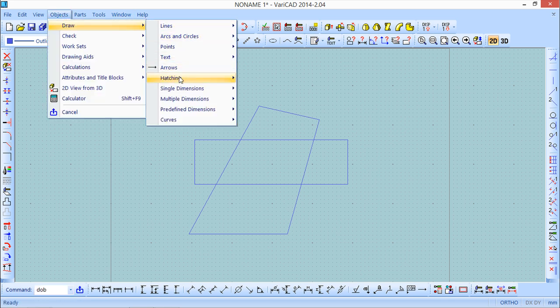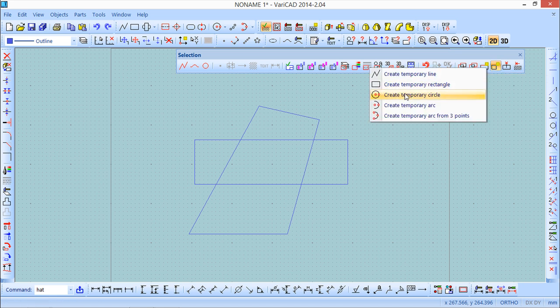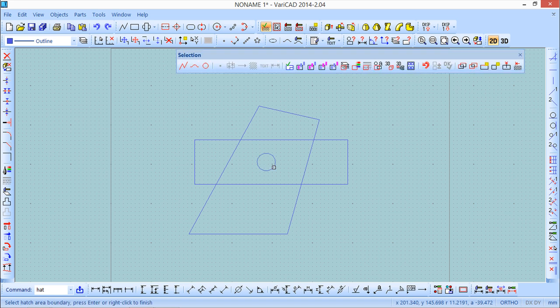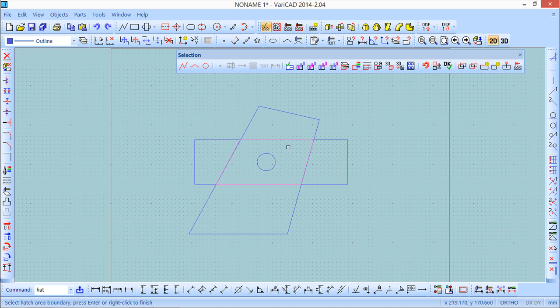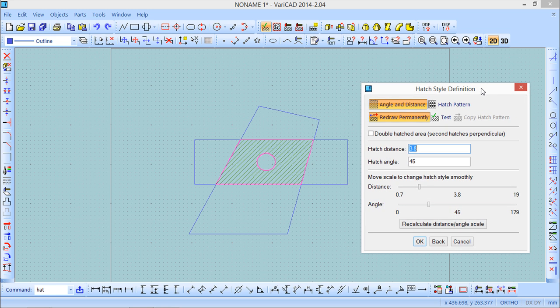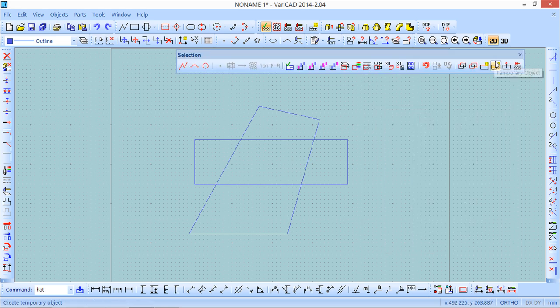Besides this function, instead of a temporary entity, we can have a temporary object. It is the same concept. If we have an area to make the pattern, for example, I can make a circle, and I can come here, and okay. As you can see, the purpose of this circle was to isolate something inside, so it was a temporary object.